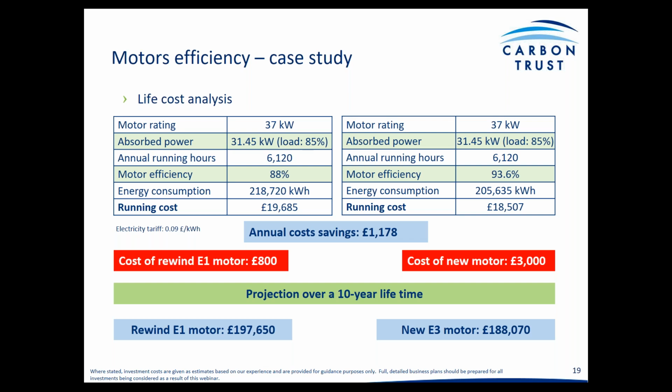Projecting over a 10-year lifetime, just by replacing the motor with a more efficient one, the energy and total cost over 10 years was around £10,000 less than rewinding the existing motor.